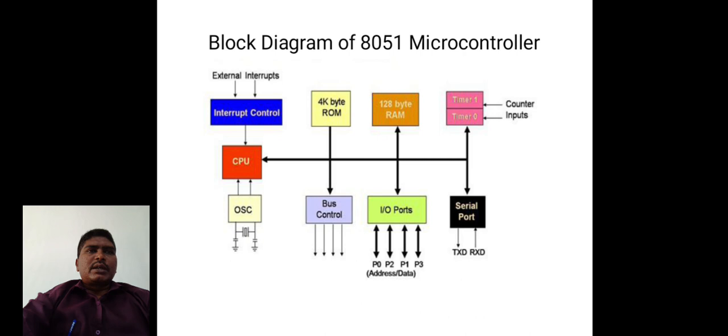The CPU is connected with one more block, the interrupt controller. The 8051 has totally 5 interrupts: 2 external interrupts and 3 internal interrupts. The external interrupts are INT0 and INT1.